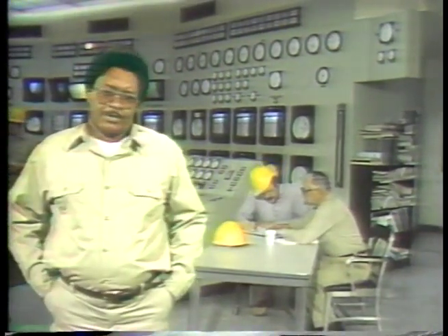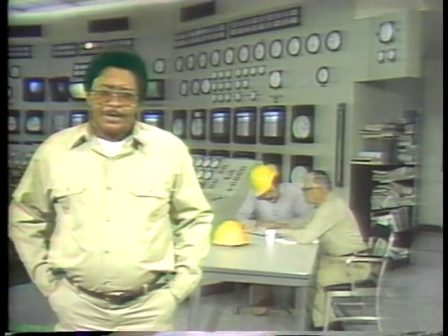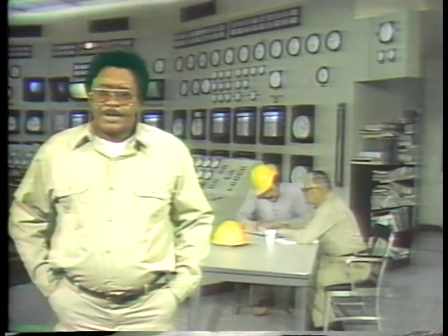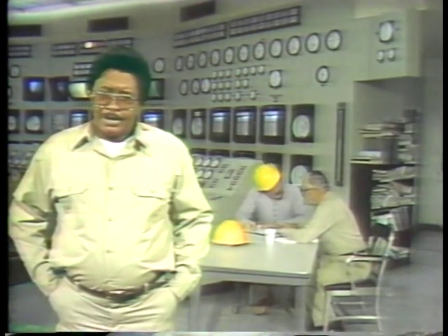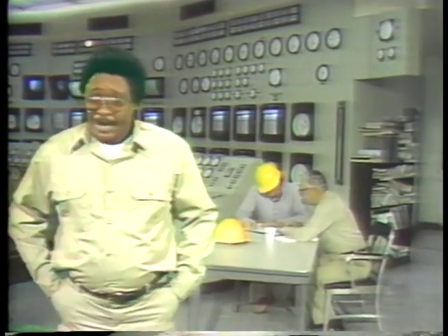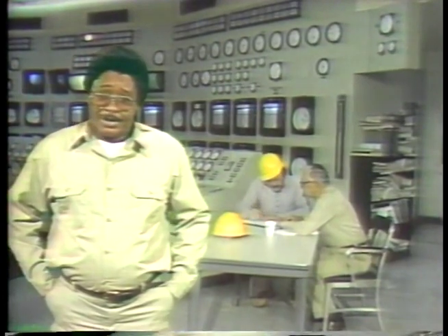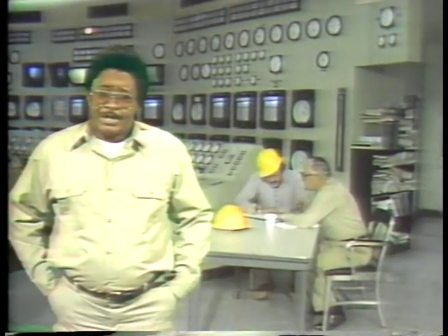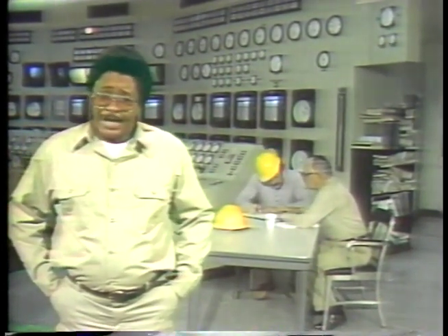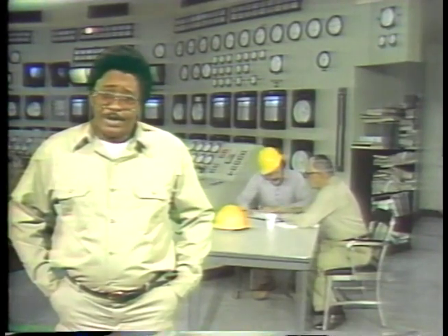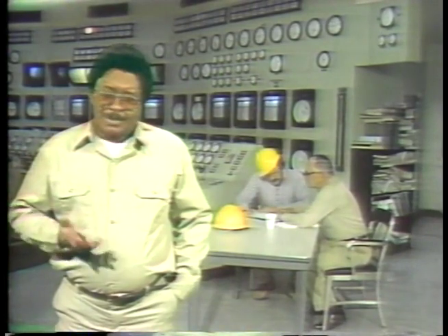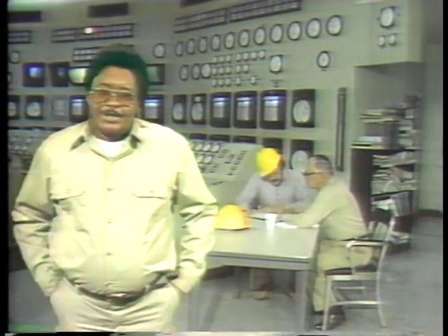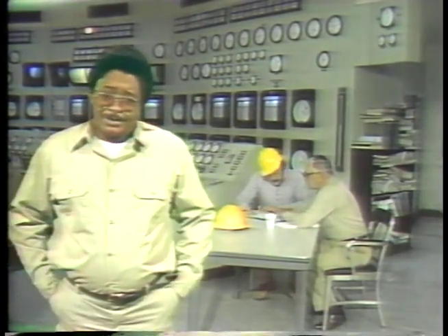A 20-year veteran of a power plant can usually look at the reading indicated on an instrument and from his experience tell if the reading is right or wrong. Now, the chances are pretty good that you don't have 20 years experience to draw on, but you still need to be able to check readings and make sure that the reading you get is proper for the system or equipment that you're checking. Where can you find this information? Well, one of the best sources that you can use are the steam tables.